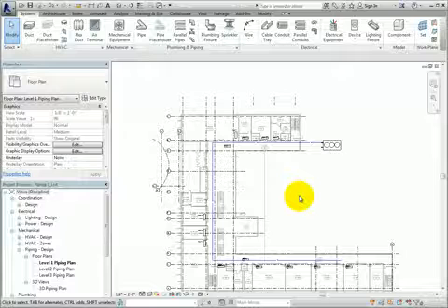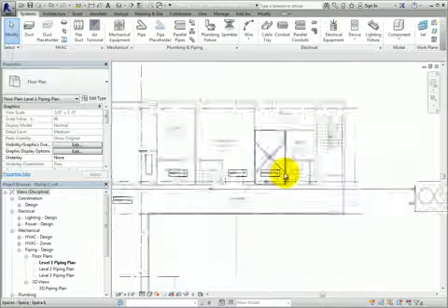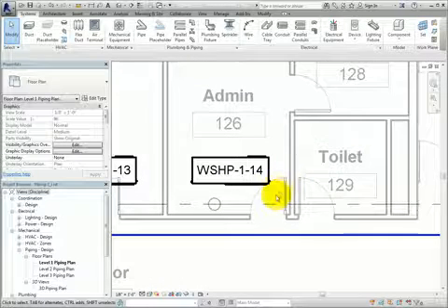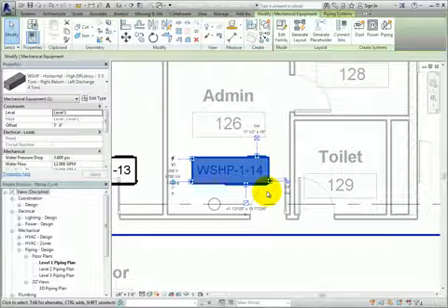The next step to laying out this piping system is to connect each water source heat pump to the main pipe. I'll zoom out and pan up to the north side of the building. I'll start with the first water source heat pump along the path of the pipe. When I select this water source heat pump, pay attention to the connector icons.